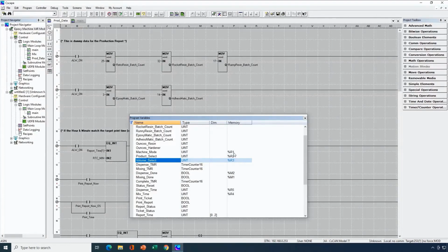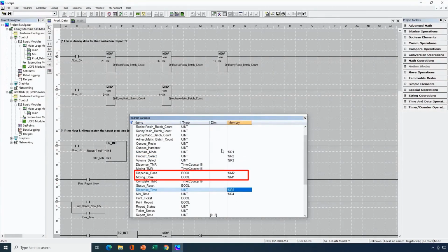With these, a single Modbus holding register read with a length of 5 words could be used to read all that data in one go. For Booleans, I have a few variables mapped into Ms. If the outside device were to read 2 consecutive coils, then they could get all the data here as well. That's all we need to do when applying a Modbus slave or Modbus server to an OCS product.